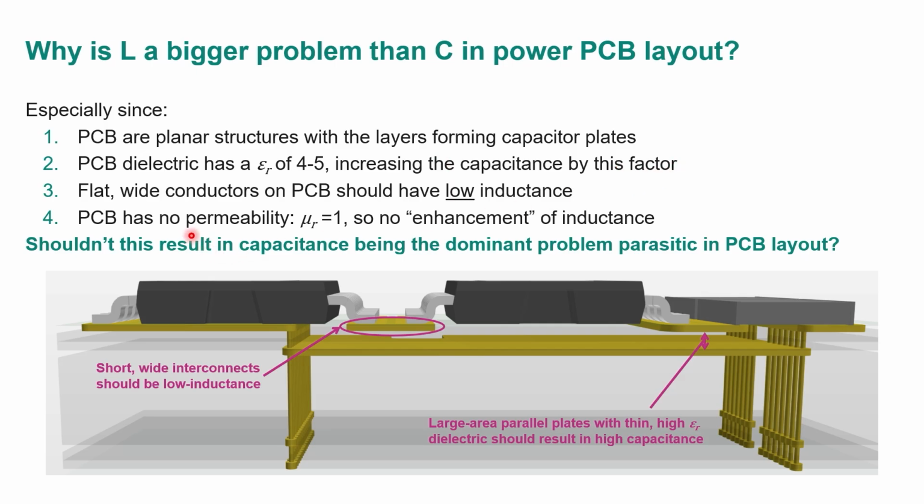And besides, there's no permeability, meaning that I don't have the same effect for inductive effects. There's no ferrite or anything here in the board to enhance inductance. So, I've got all these parallel plate capacitors with dielectric, wide conductors. This should all point to capacitance being the problem rather than inductance.